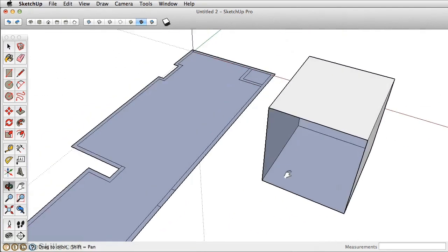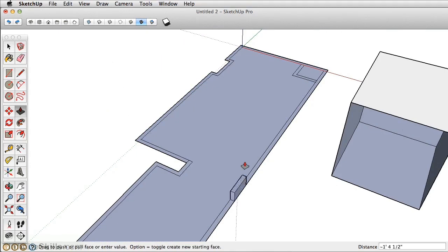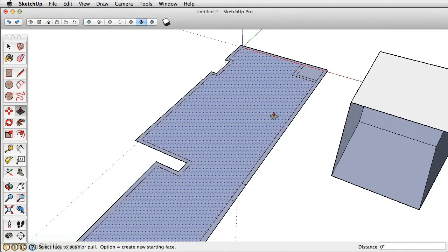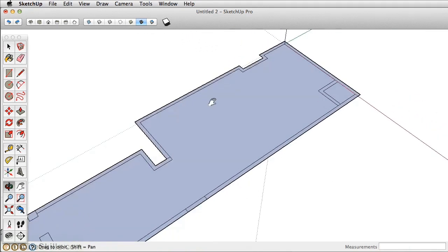And there's a glitch that happens sometimes in SketchUp where you extrude a wall and it brings up the inside faces the wrong way. And it's just a common error in SketchUp. It's not very critical if you're just modeling within SketchUp and you end up just applying textures. But if you're using other programs or exporting this into other programs, the direction of that face is very important.